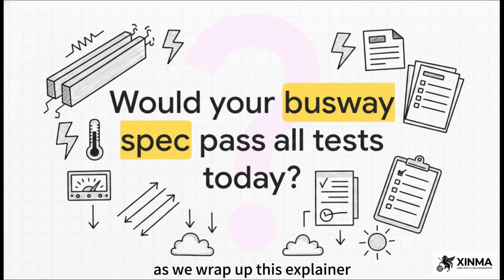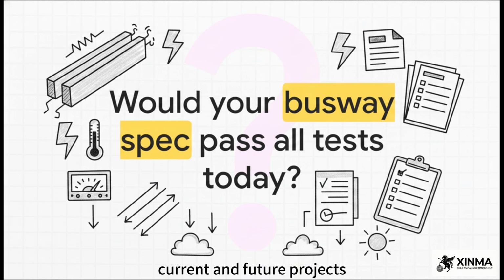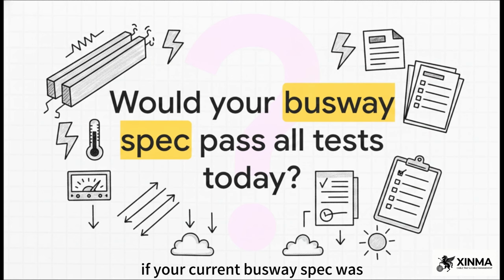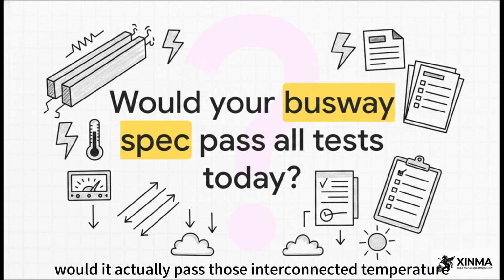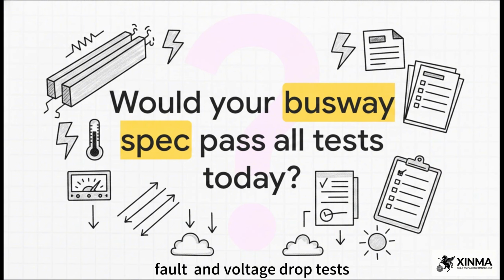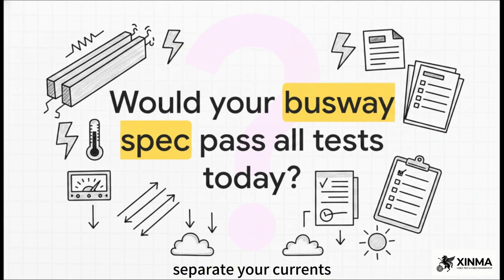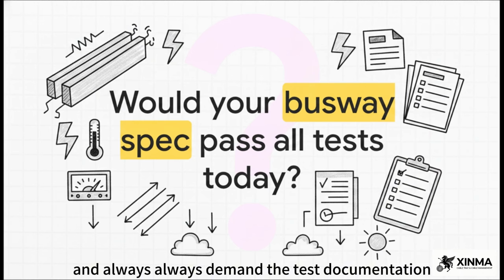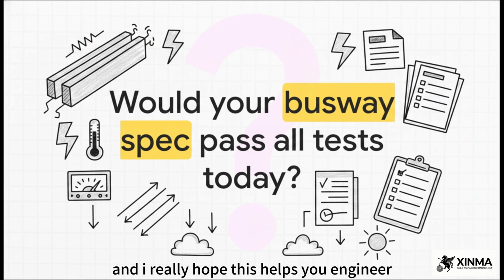As we wrap up this explainer, I want to leave you with a bit of a provocative thought, something to really apply to your current and future projects. Think about the design sitting on your desk right now. If your current busway spec was comprehensively reviewed today by a third party, would it actually pass those interconnected temperature, fault, and voltage drop tests? Or did you just select the next standard size up? Just remember, separate your currents, apply your environmental re-rating factors, and always demand the test documentation. Stick to the checklist. Thank you so much for joining me for this explainer, and I really hope this helps you engineer your next project with absolute confidence.